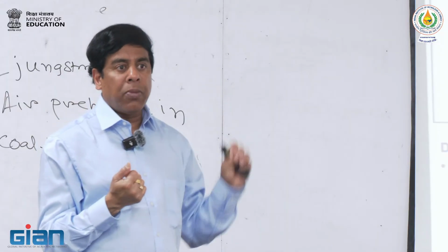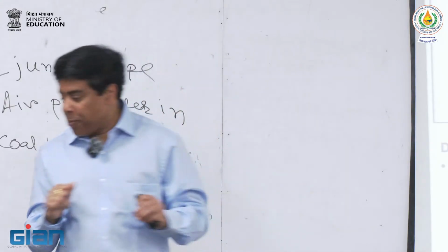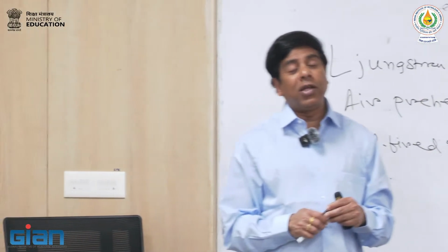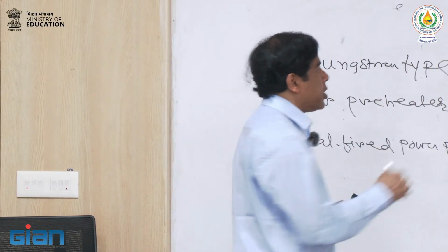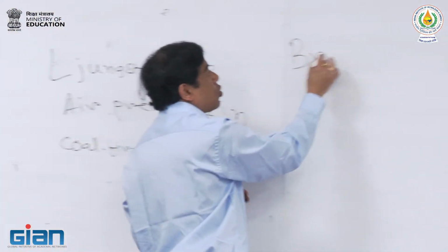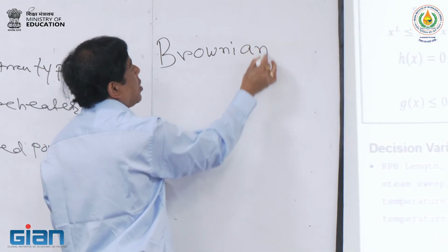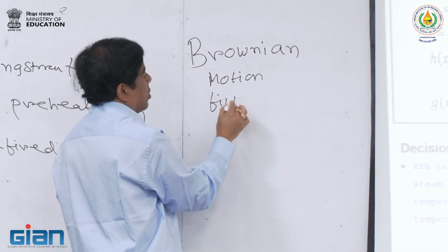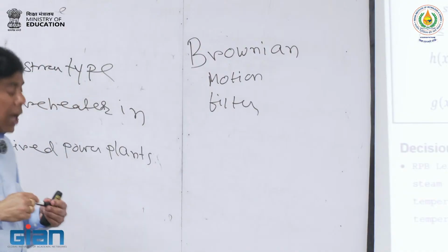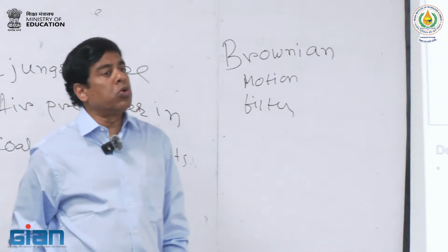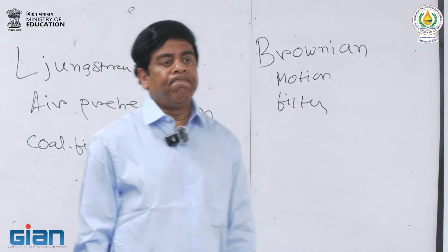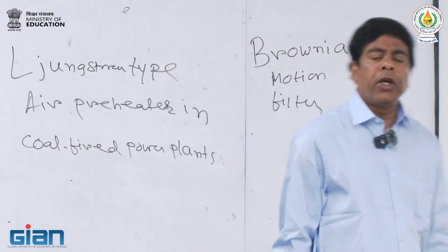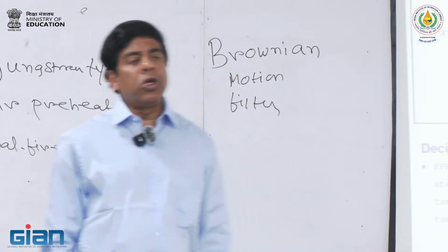For these systems, including solvents, not just sorbents, there are other filters people use. There are ceramic filters, and I know in TCM they installed one, because they use the RFCC regenerator gas. RFCC regenerator gas has catalyst fines in it, and it's very difficult to separate. So they have, you can read about it, it's called a Brownian motion filter. That actually takes most of the particles out. You should not send any of the solids to the bed.